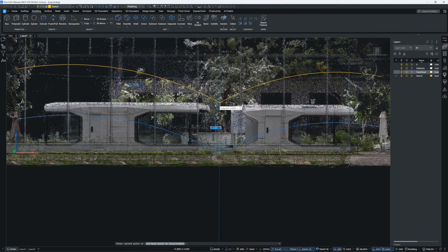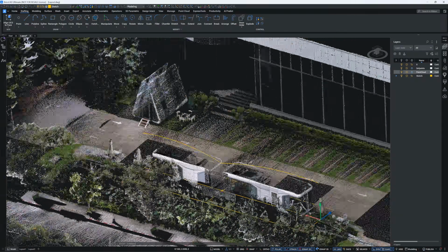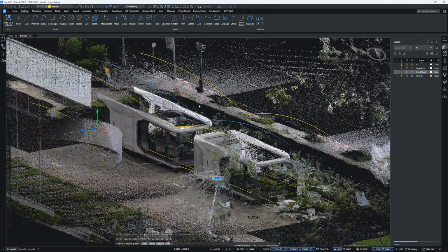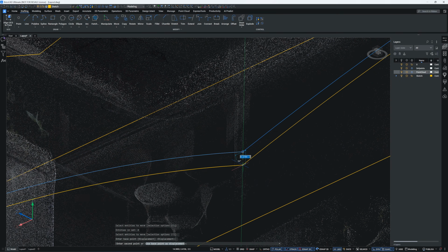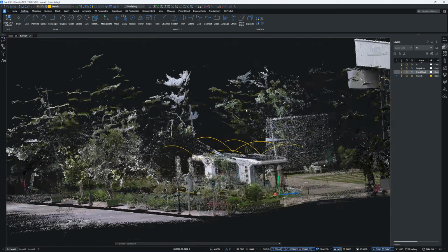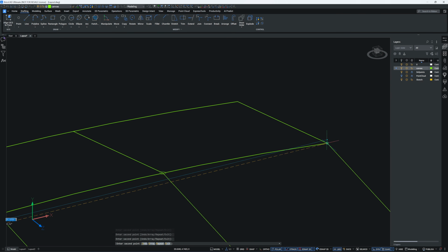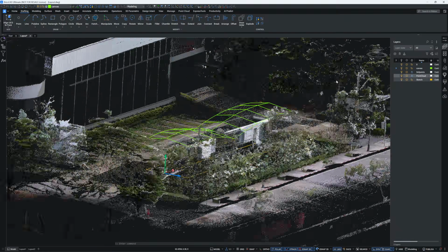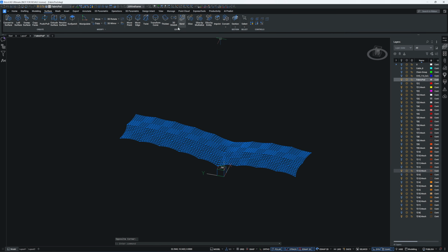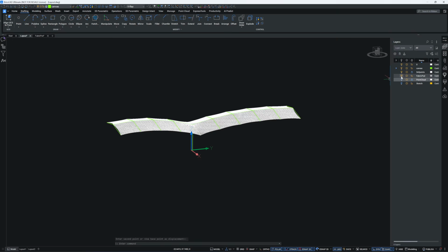I have worked out the roof form and adjust the height. You will notice I orbit back and forth quite a bit to evaluate the proper roof shape in relation to the surrounding environment. This is my workflow for designing canopy structures. I start by defining the roof boundary, then create the roof forms using 3D lines. Those lines are used to run the calculation model which generates the tensile fabric shape. This fabric shape was simulated in dedicated software, then imported into BricsCAD.